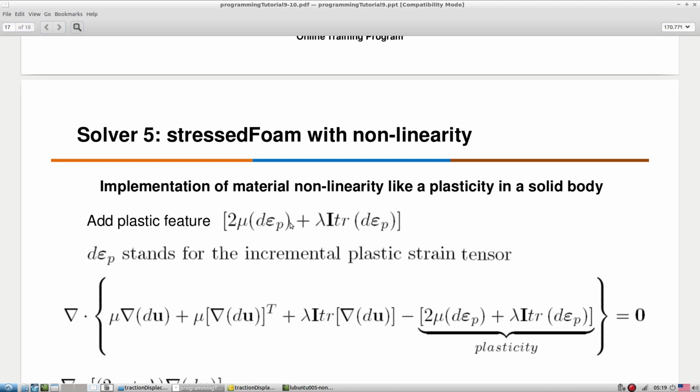If we look at its proper definition, perfect plastic is something like that, where there exists a maximum level of stress that the solid body can handle elastically. Once the maximum level is reached, after that the solid will undergo irreversible deformation without increase in stress or load. So it starts deforming irreversibly without any incremental load. That is what is called its limit. That is the limiting property we are required to restrict. Up to that it is elastic, and after that it is the plastic behavior.